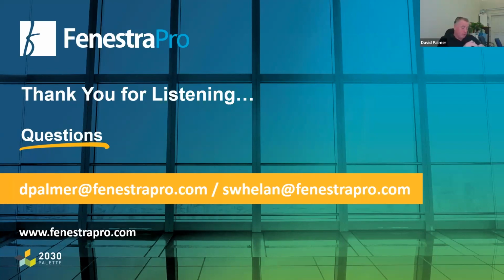To answer your question, Simon, you're a LEED Green Associate, if I'm not mistaken. I would say it's not a LEED reporting tool. Fenestra Pro is more of a design tool, and it's not negating any kind of more detailed energy modeling or more complex analysis to drive some of that compliance. I think Dave touched on it there. We don't calculate daylight autonomy. We do just very high level design daylight factors. But there's lots of data you can drive out of that, and that's probably the best way. We could talk about it offline. I'm not sure who asked that question, but we could.